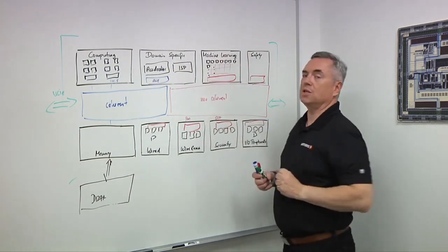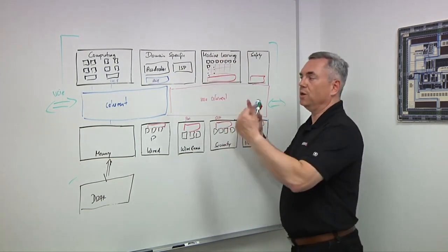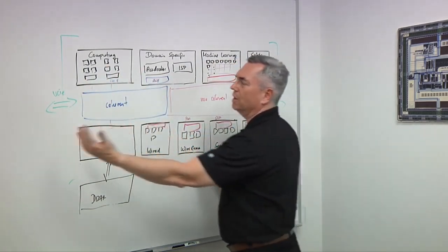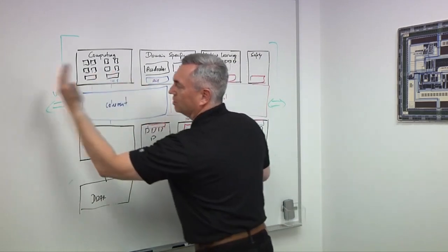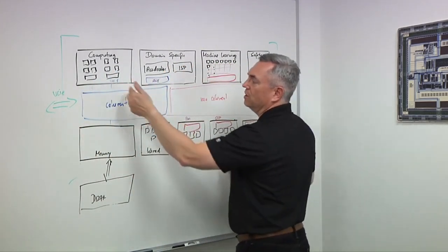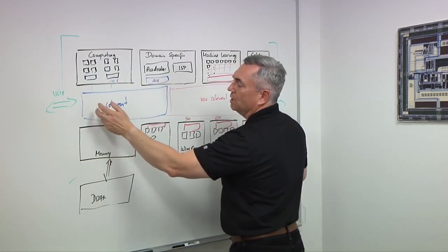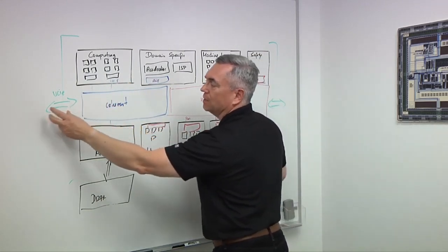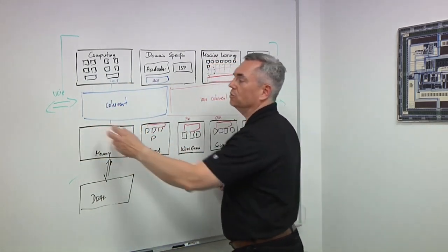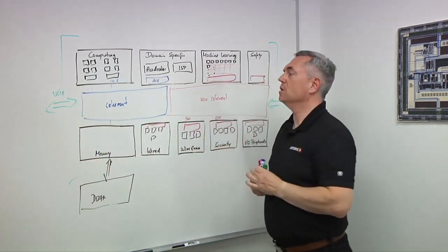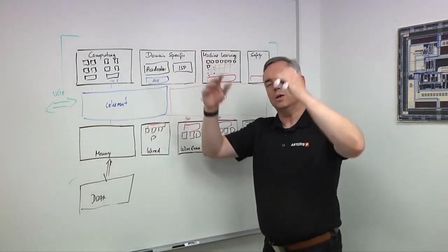So these connections need to be done first before you even think about the connections to the outside, which is really an architecture choice, because this might just flip on the other side, and you need to figure out which of these protocols do you then actually package and transmit over the chiplet interface using UCIe, perhaps with a CXS streaming interface. So that needs to be done at a top-down architecture level.